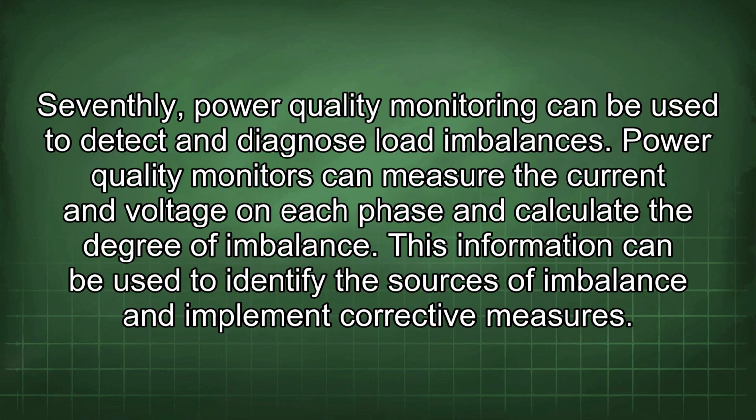Seventhly, power quality monitoring can be used to detect and diagnose load imbalances. Power quality monitors can measure the current and voltage on each phase and calculate the degree of imbalance. This information can be used to identify the sources of imbalance and implement corrective measures.